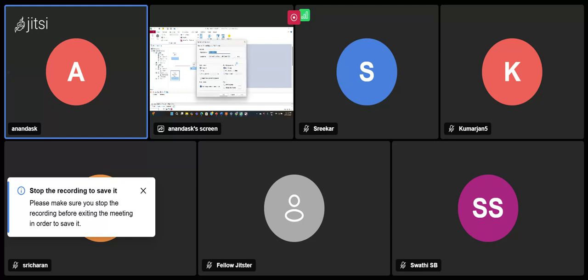After that, the configuration, the CAN option. Then again, you should start here. Then it will replay the log which you got from the vehicle, and you can see that log in the trace window. Now nothing is there because we don't have a log. Any more information regarding the replay block?